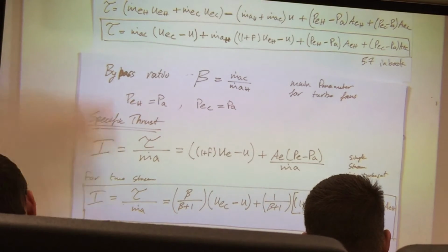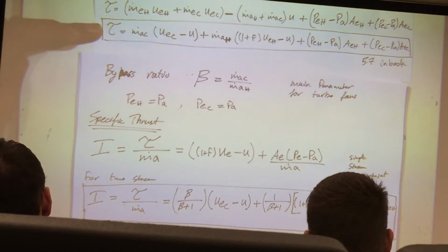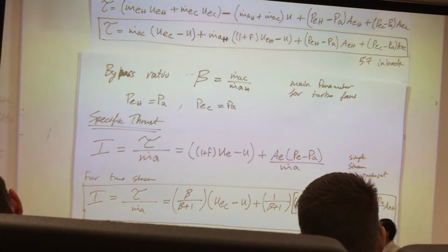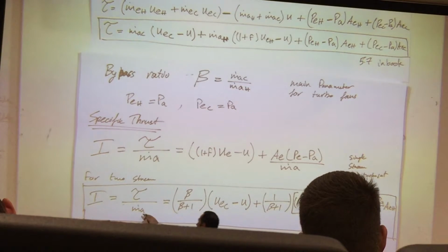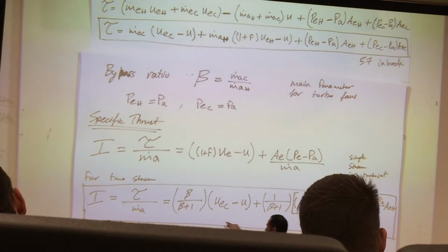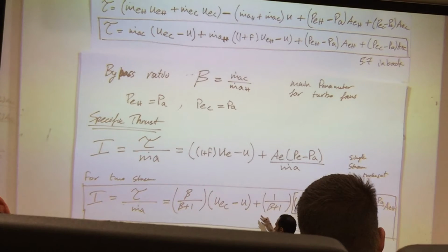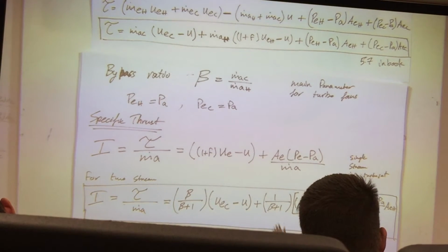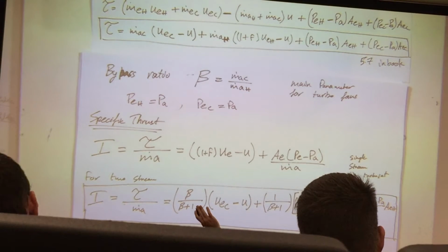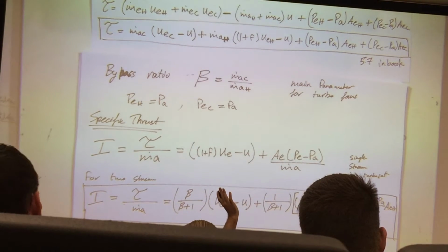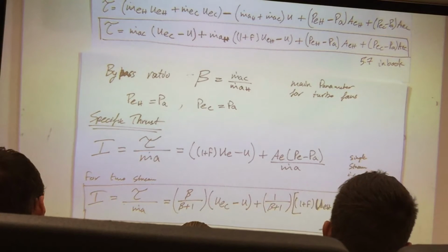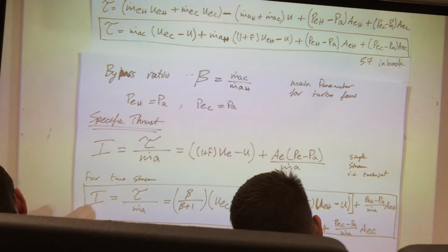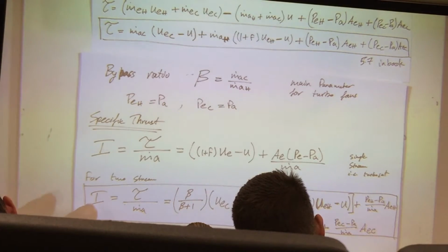And all it is, is the same thrust equation that we just derived right here, normalized by how much air I'm really inputting into my engine, and what is my bypass ratio, which drives how much, think of it this way, how much am I doing for my fan versus how much am I doing work through my core from a thrust perspective. So based on this, let's define some of our key parameters for our engine. So these are the basic principles.